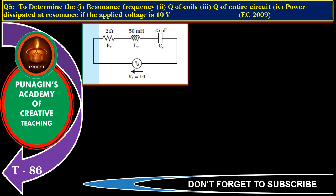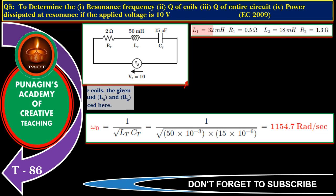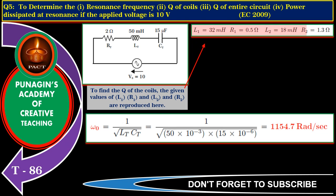Friends, the circuit drawn indicating the values of RT, LT and CT obtained is shown here. To find omega naught, we know omega naught is equal to 1 divided by square root of LT into CT. By substituting the values and solving, we get omega naught is equal to 1154.7 radians per second.